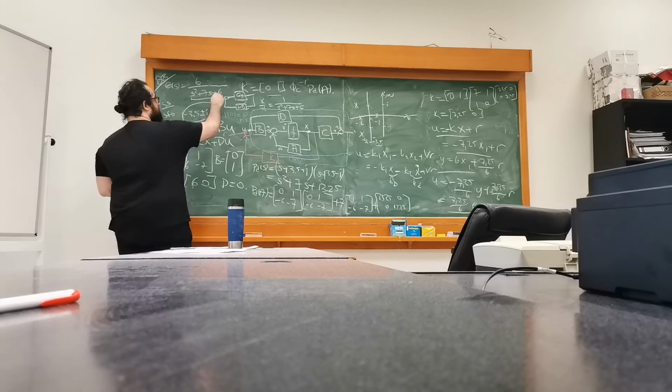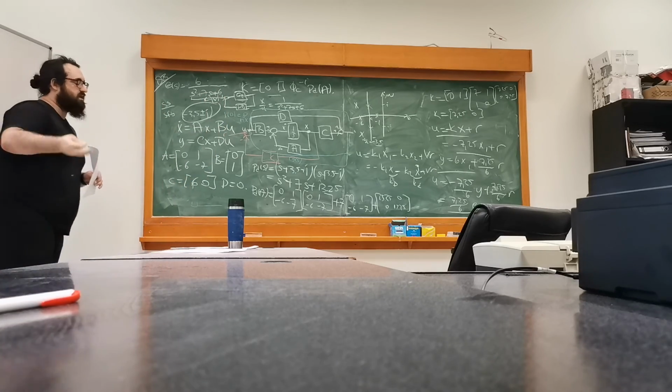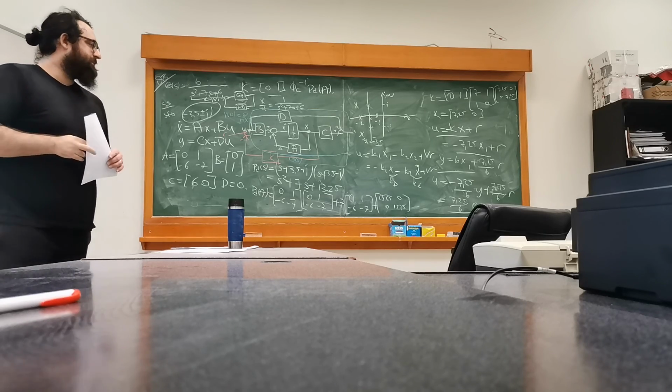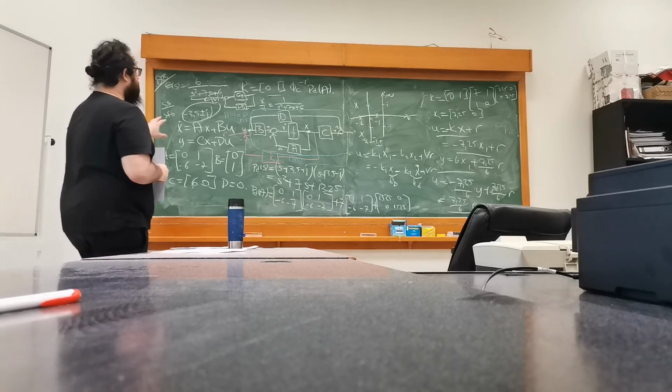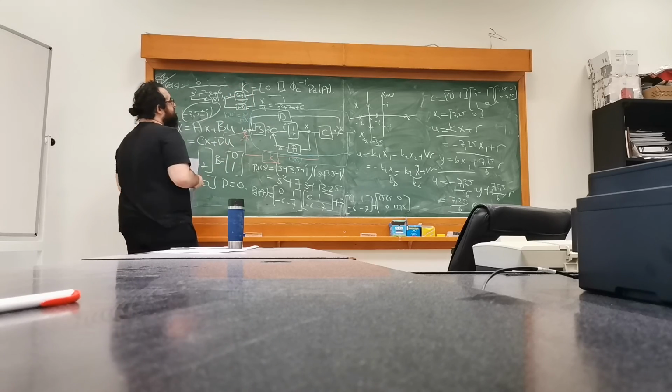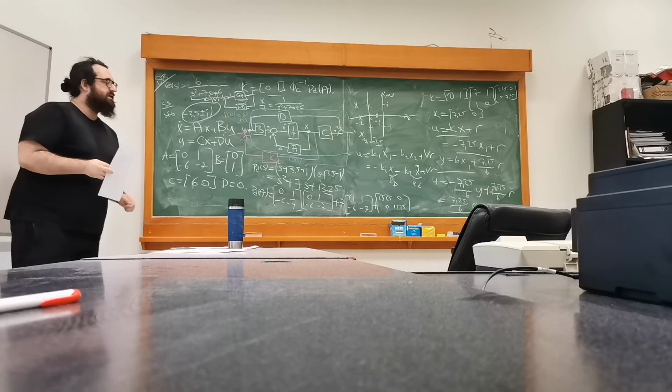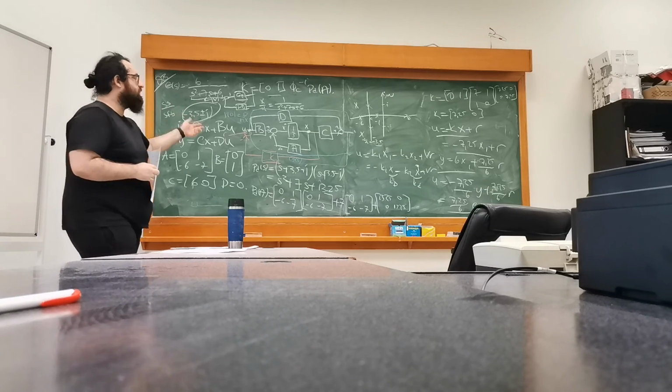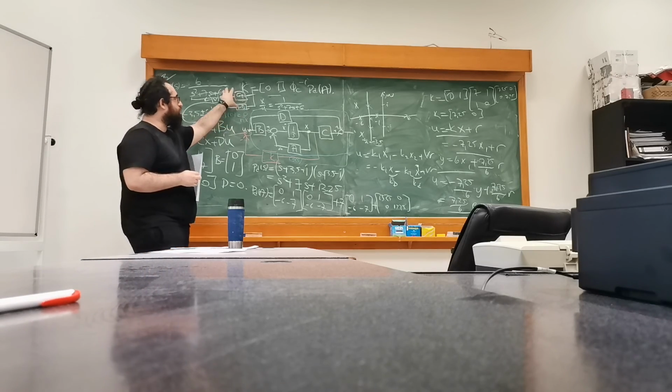Therefore, I have V times R, something like this. So R times V, you have an amplification. But it's not the best control strategy, because if you have a certain output disturbance or input disturbance, you would not track the output. It's a semi-closed loop approach because you're just changing the pole locations.